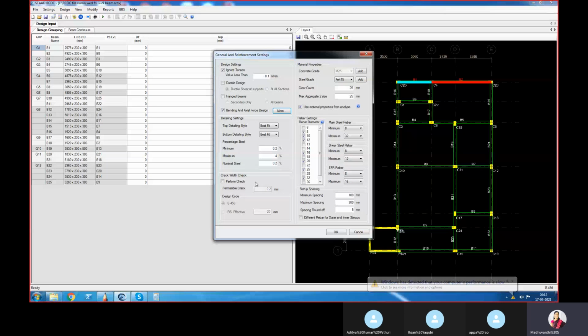So generally there are two types of cracks, right? One is the thermal and the other one is shrinkage crack. But for the slab which we have done earlier in RCDC, we would have given for both thermal as well as the shrinkage crack. So here it is asking only the shrinkage crack, right? So since slab is a very big element, because of that, it will be subjected to thermal crack, right?